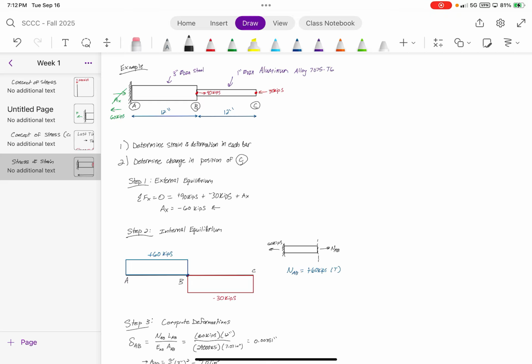Right. Yeah. And then I asked you to determine the stress at that cross section. Right now we did in class with this question. Right. Because I feel like these are similar. Yeah, they're identical basically. So just cut a section and draw out how the holes would look in that cross section. What did we determine from cutting the cross section? The rectangle. It was rectangular in cross section with dimensions of the diameter times the thickness of the material.